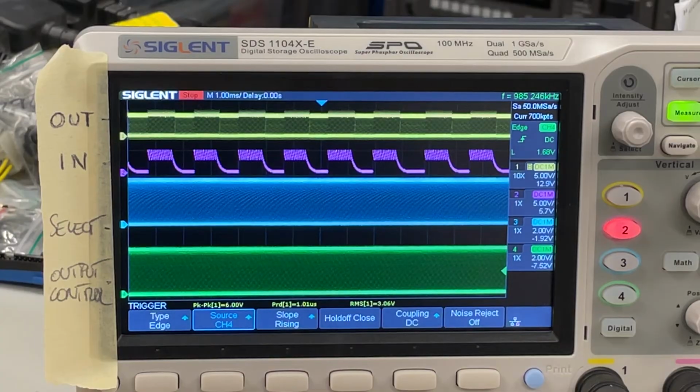It feels weird. I appreciate the oscilloscope is introducing some impedance, but especially on a 1983 device, I wouldn't expect something to be upset by a modern oscilloscope's probe, to be honest. So, because I don't know about this, I think the only way to check whether there's something wrong with this chip or not is to check a working C64 and see whether it shows the same behavior.